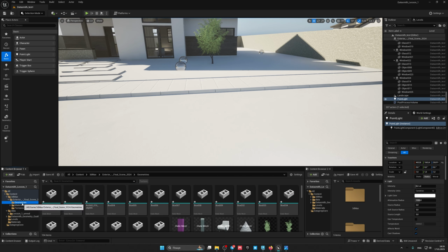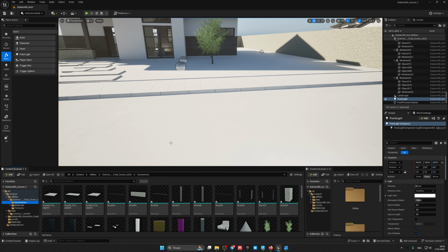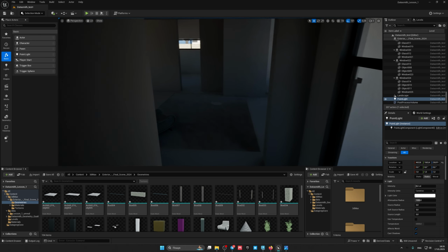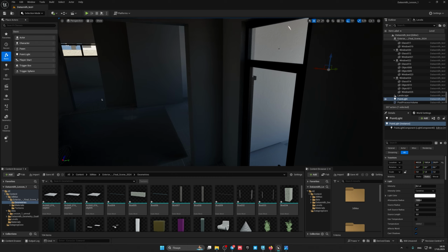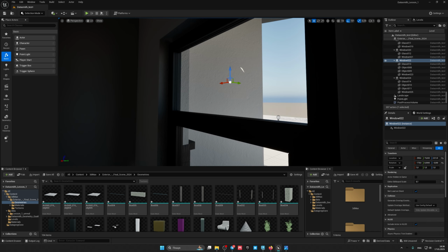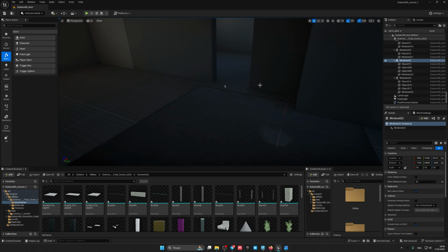But if we go to the folder with geometry that came to us from 3D Max, we see that we have only 104 objects from the geometry itself. So all the other actors, these objects, which are now 207, mean there are practically 100 extra objects. Some kind of incomprehensible clutter. And these are all our groups. So each group, after 3D Max, will hang in your scene as these small objects, which are sometimes not even visible, but you can select them, and they will interfere.